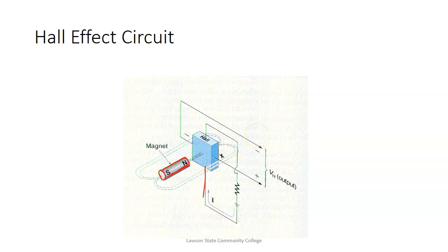We'll look at the standard color codes on this in a minute. That's important to know too when you wire these things up, and they're not the same as what we use over here. So what we would do now is go over there and identify all the Hall effect or reed switches. We don't know what they are until we look at the prints, and we'll show y'all the actual symbol that we use on the prints to represent these.